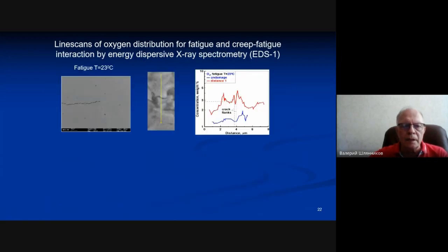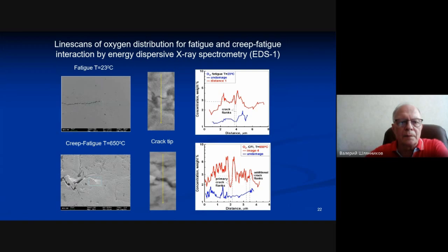And the last slide of my presentation, so I am nearly finished, is the comparison of oxygen distribution for fatigue at room temperature and creep-fatigue interaction. And you can see that the holding time at creep-fatigue interaction intensifies the diffusion process and accelerates damage processes.